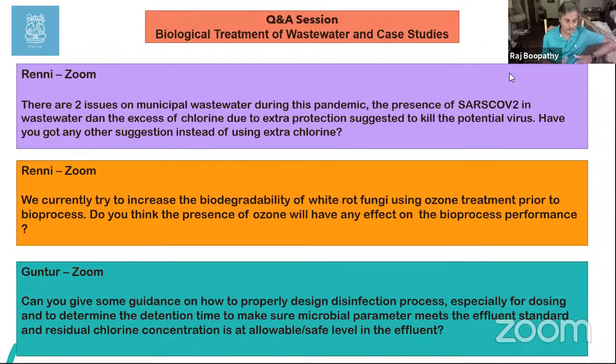So this is for municipal wastewater? It depends on where you're letting the wastewater out. If you're letting it out into a wetland or a river, less than 0.5 ppm chlorine should be okay. The residual chlorine shouldn't be a problem. But to know what dose you need to kill most of the microbes effectively, you should do a simple small-scale design in the lab to figure out how much chlorine you need.